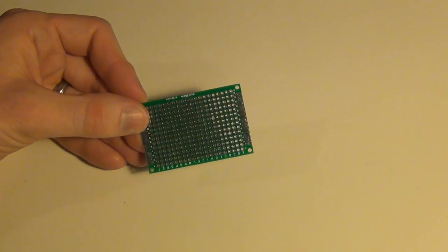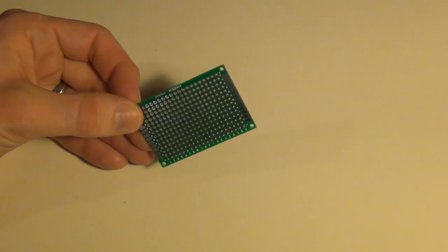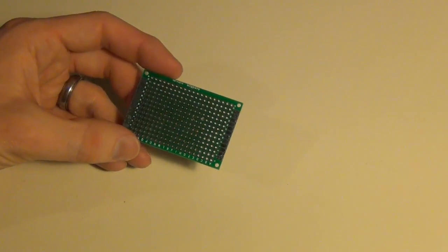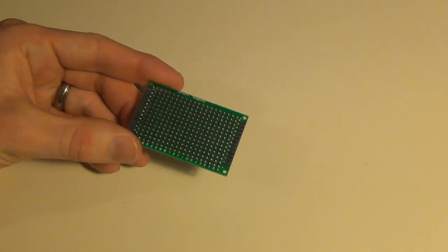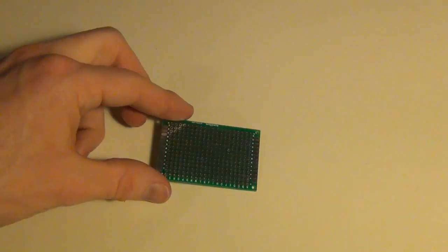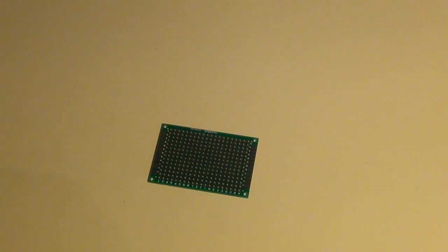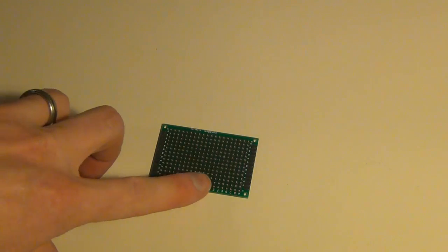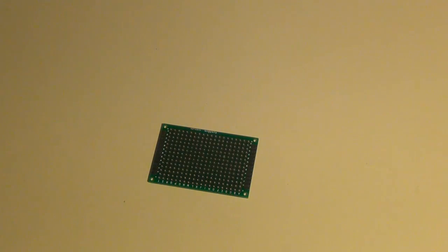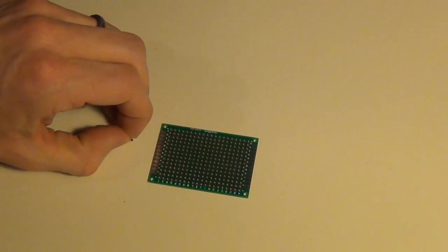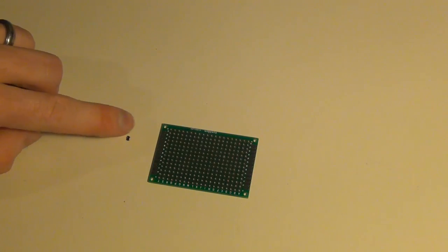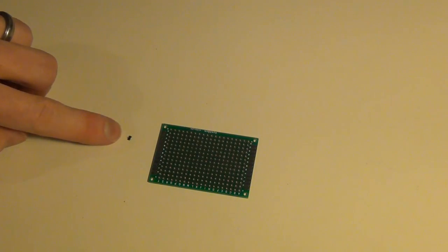So I already mentioned double checking your connections to make sure they're correct. But another thing that I run into is, and you'll notice this if you've watched any of my other videos, that I use these prototyping PCB boards here. So those require soldering and then smaller wires. So I've actually had it where it looks like my solder was correct. You know, I could see it and it looked like it was all correct in there. But it actually was a bad solder joint, so it didn't actually make a connection. And I solder in things like this tiny little 3.3 voltage regulator, so it's really hard to get it soldered correctly.